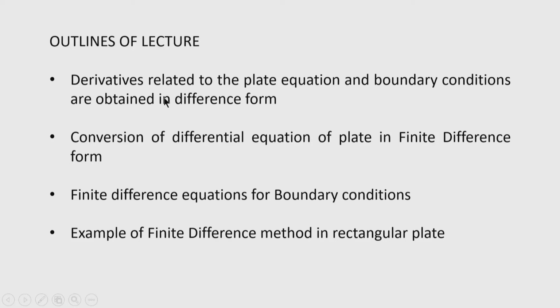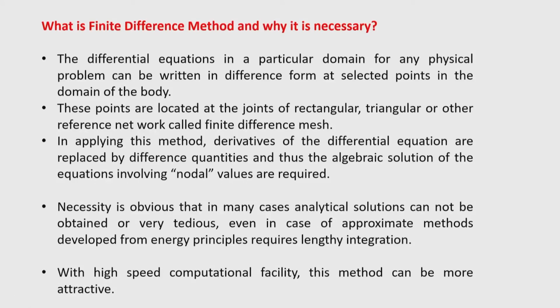First, I will find the derivatives related to the plate equation and boundary conditions in difference form. Then, I will convert the differential equation of the plate into finite difference equations. Finite difference equations for boundary conditions also have to be developed. Lastly, I will illustrate an example of a rectangular plate whose deflections are found using the finite difference method. Now, let us see what the finite difference method is and why it is necessary.